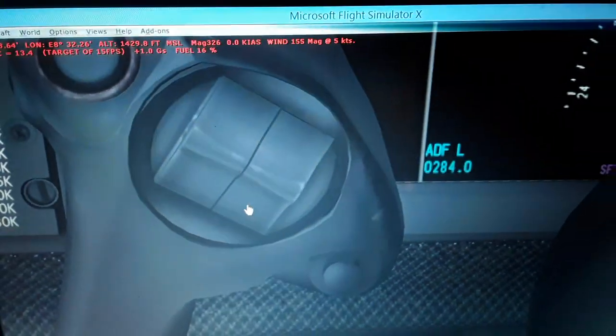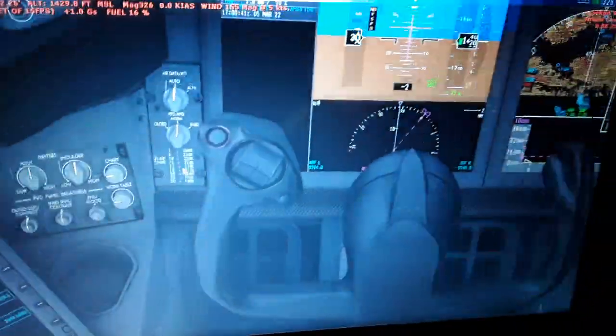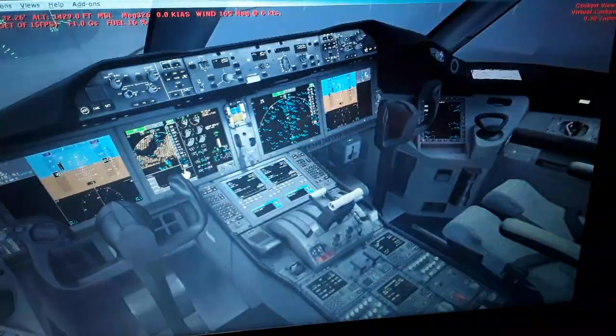When fine, you trim this way or the other for balancing the aircraft in flight, to relieve the air pressure from the flight controls and the yoke and have more balance in flight. We can keep a pitch up or pitch down nose attitude of the aircraft, whether you want to glide, descend or hold level flight. So you would see also that. You also have more flight controls.